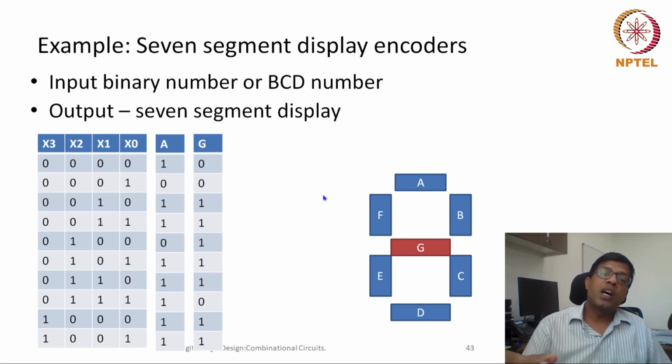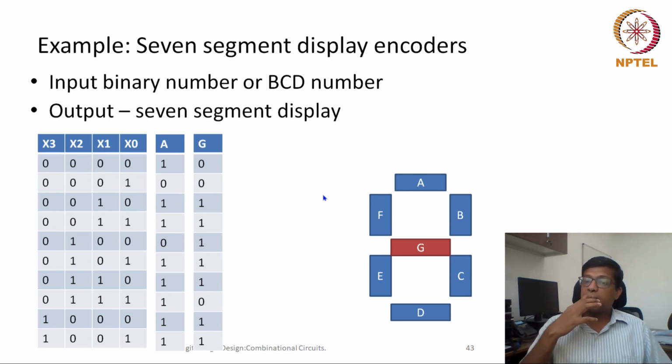So this way, for all these 7 segments I need to write a truth table, do K-map optimization, and then finally solve the circuit, so that I can have an optimized circuit for all of this, A to G. So this is for BCD. This 7 segment display, as I said, can also be used for other numbers, like hex numbers, and even some alphabetical characters.